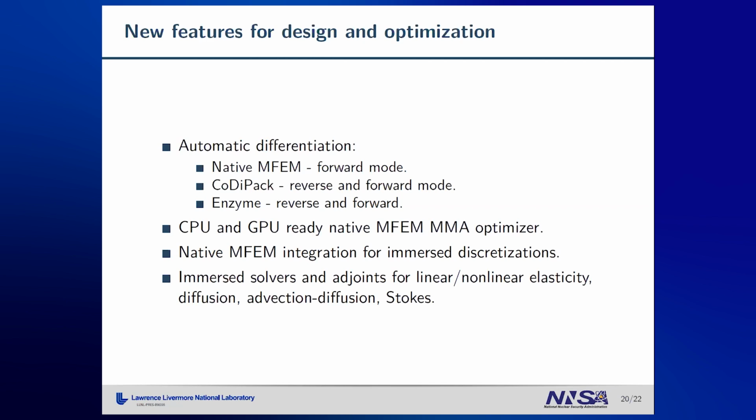Now we are preparing a PR of a native method of moving asymptotes optimizer in MFM, which hopefully would be GPU ready at the end of the next year. We would soon push a PR on a native MFM integration for immersed discretizations. And we are working on immersed solvers and their adjoints for linear and nonlinear elasticity, diffusion, advection-diffusion, and so on. Thank you very much, and any questions are welcome.